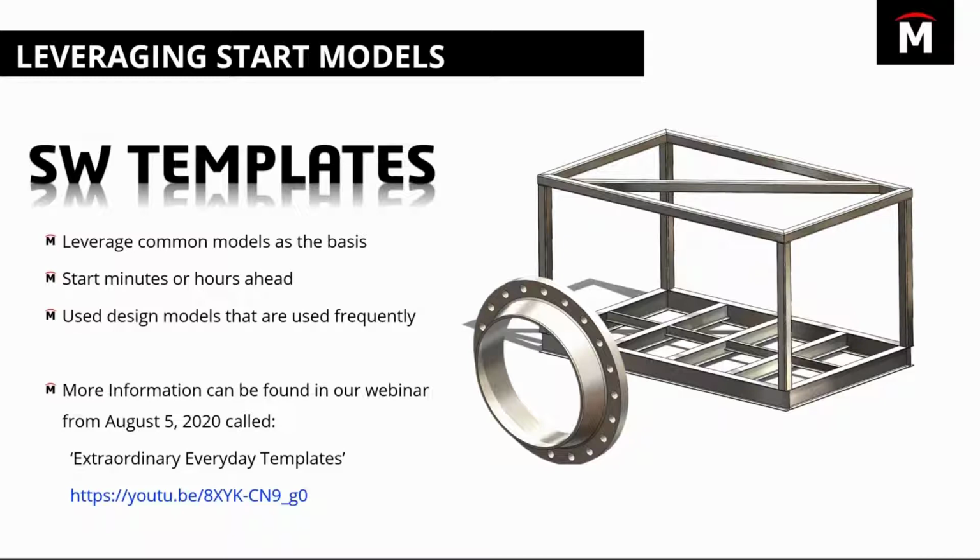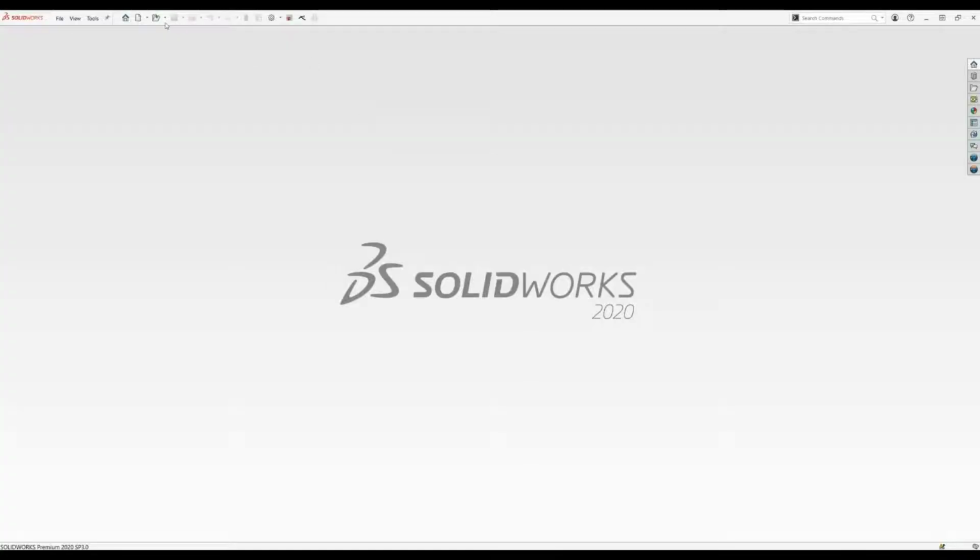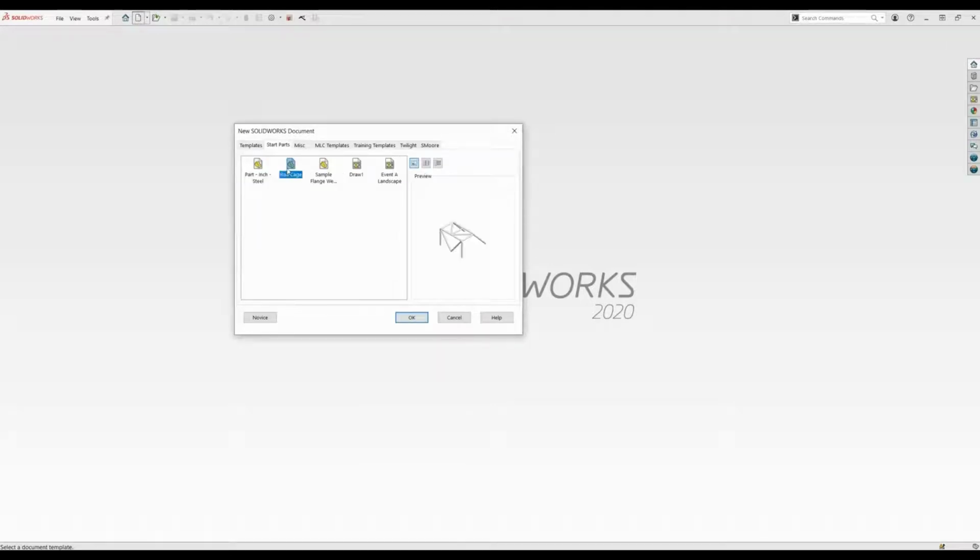Now, some of the things that we create inside of SOLIDWORKS are the same but different, and they're very simple models. Maybe they're a round shaft, or maybe they're a skid like I have shown on the slide. And in this case, the one that I'm going to use is a roll cage, right? Now, obviously, I'm sticking with the car theme for this presentation, and so we want to use a roll cage, but I want to change a few dimensions, and I'll save that into my project. Now, those types of templates can be used and leveraged very, very easily. And it's just by taking and creating the geometry once and then starting a new part with that geometry.